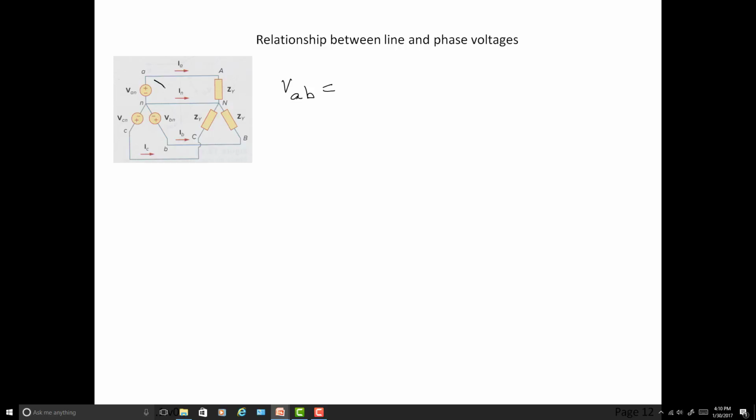We're going to want to find this voltage across here, right? Something that looks a little more like the delta. But we're not doing a Y-delta. We're doing a YY, but it doesn't matter. We're finding the line-to-line voltages because that's always helpful to have, and that's always what's going to be out on the power lines. That's always what's going to be going on out there.